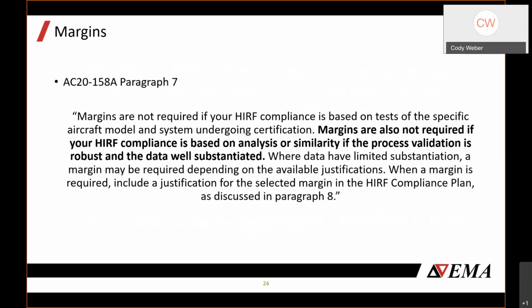Okay, last point here with the lengthy text, I believe, is associated with margins, because anytime you do numerical analysis, there's a margin conversation that comes up. I particularly like the margin assessment that is used in AC20-158. It says that margins are not required if your HIRF compliance is based on tests of the specific aircraft model and system undergoing certification. Margins are also not required if your HIRF compliance is based on analysis or similarity if the process validation is robust and the data is well substantiated.